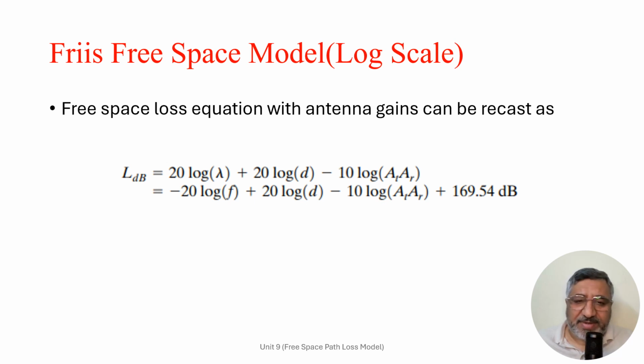It is interesting to compare the free space model equation with the Friis equation. The free space equation indicates that as the frequency increases, the free space loss also increases, which would suggest that at higher frequency, losses become more burdensome, which is not true. However, the Friis equation shows that we can easily compensate for this increased loss with antenna gain. In fact, there is a net gain at higher frequency, other factors remaining constant. So in other words, the Friis free space equation is a little advancement compared to the free space model to design and model wireless communication systems.